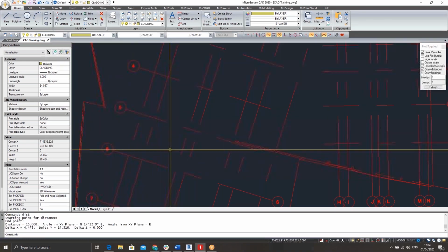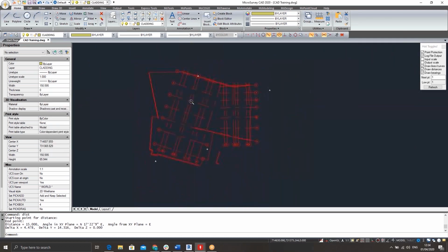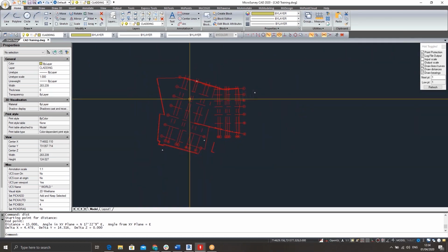So we can see 15 meters, so 2 grids across, 7.5. So we manipulated, we froze layers that we had of interest. Then what we did is we could thaw the layers, but delete the remaining information first that we're not interested in. So what I will say is that you always want to have your information saved in 2 or 3 different places. So I'm not going to start manipulating the drawing and altering that CAD file unless I know that I have the source information in an email or somewhere else saved.